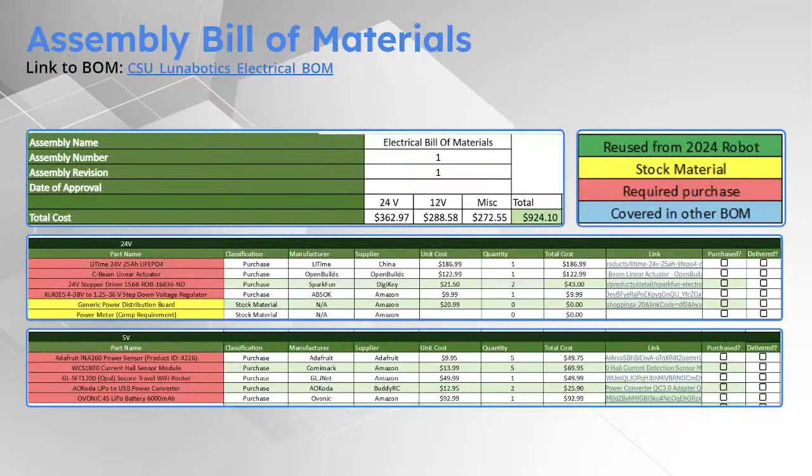So, if you're worried about pinch points, these kill switches are industry standard. They're used in industrial settings. They're extremely safe. As far as shorting the battery, that is definitely a safety concern, and that's mostly handled. It's going to be in the plastic box whenever you're handling it. A lot of that is good connector design and harness management, where you can intentionally design it to make it hard to short. The connectors are only going to go in one way. They're recessed connectors, so you can't set it on something and have it short out. The only other thing would be getting it pinched on something, and if you're following the rule of working on it while the kill switch is on, it shouldn't get pinched.